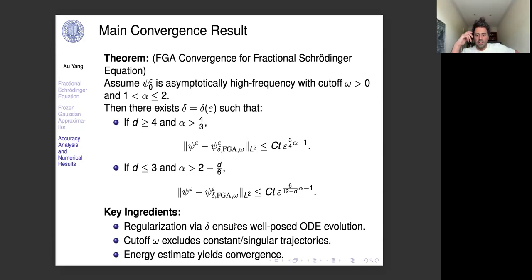Okay, because I think sometimes in these kinds of numerical settings, you somehow implicitly end up imposing the regularizations even if you don't do it. The method itself will somehow impose these regularizations. For example, if you use RK4 as the ODE solver for solving the ODE equations, then you have the numerical dissipation that is introduced there, and it may save you out of the blow up, but sometimes that's kind of a linear stability issue, right?